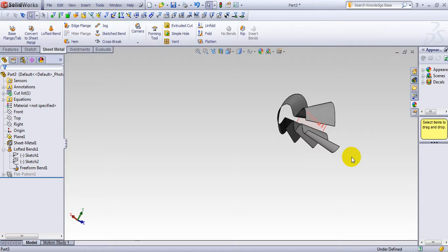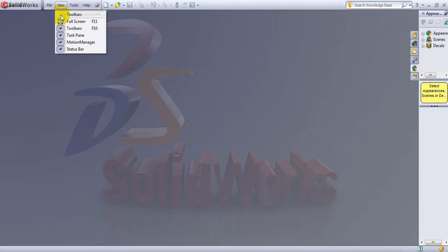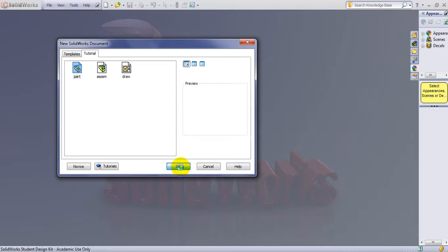Now, as mentioned, there are a couple of things you have to be very careful about. Number one is when you do loft, unlike what we had in normal lofting features, you cannot loft a closed sketch.